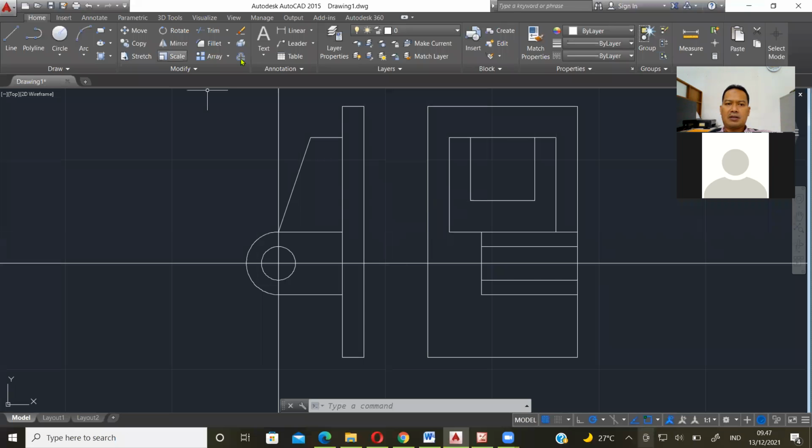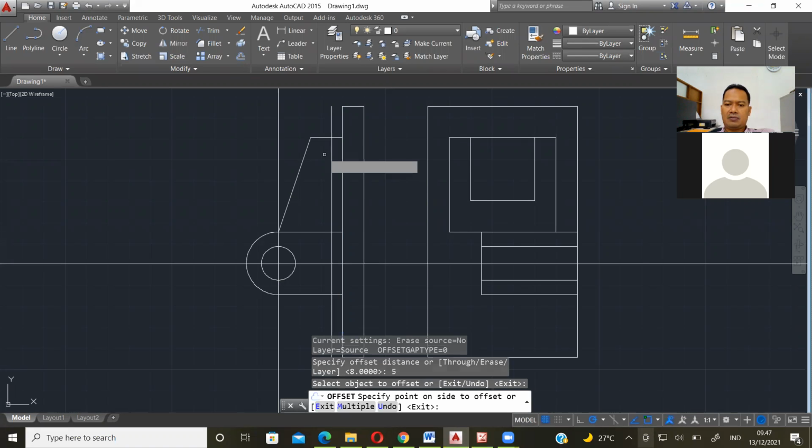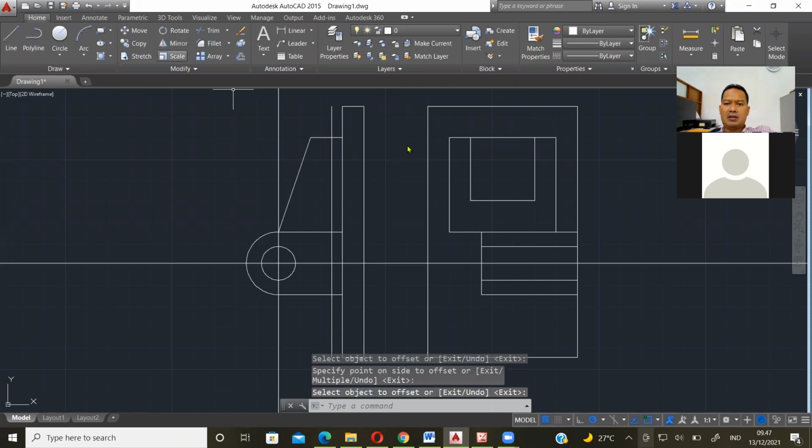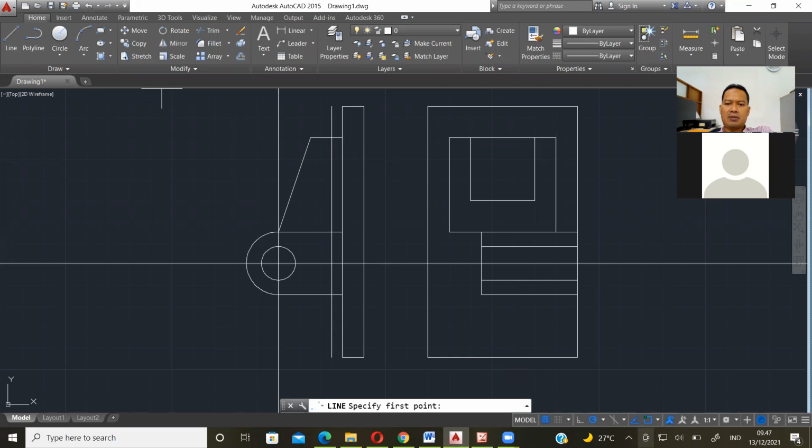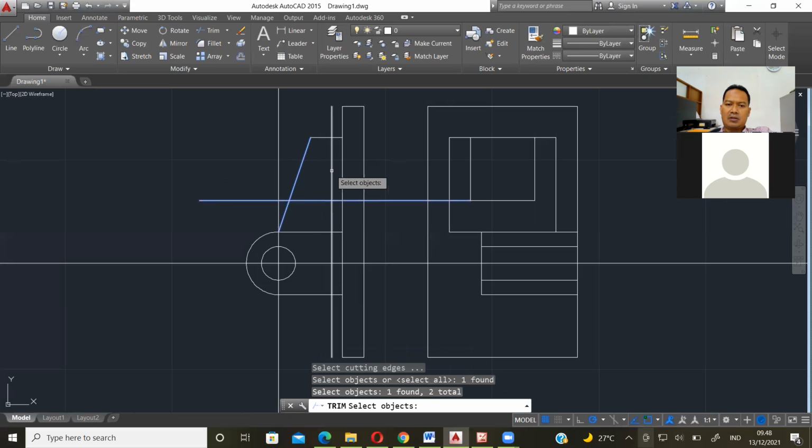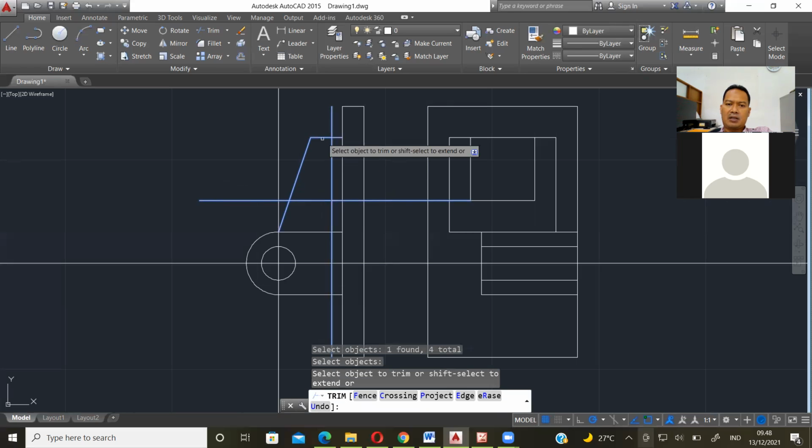You can offset in millimeters from here on the left, and then on the horizontal you can create from the endpoint to left side. Create line, this one, from the endpoint to the left with the horizontal line, and then enter to finish. Cut by using trim. This one, and this one. Right click and then click the unnecessary line.